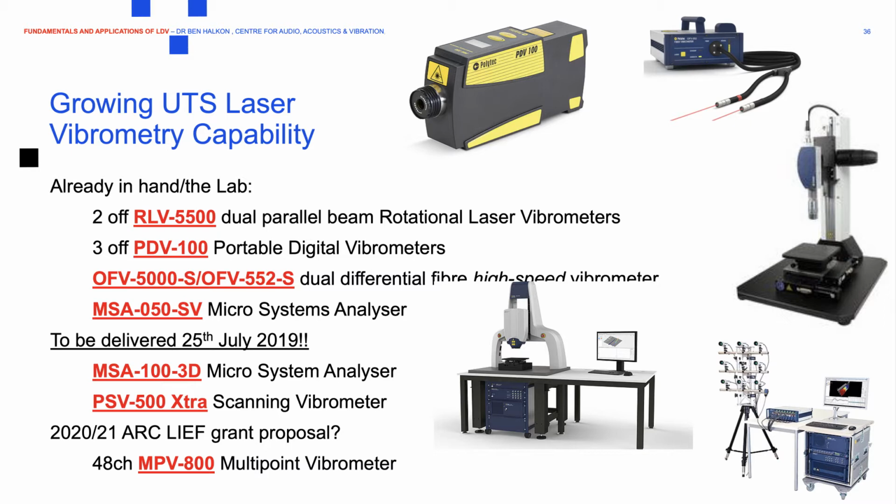So I mentioned previously that we have to take care with matching of path lengths, and we often have to treat our surfaces in retroreflective tape. With this device, it's a high powered laser, it's invisible, and infrared is absorbed by the human eye, so because it's absorbed, it's still class 2 even though it's a 10 milliwatt laser. And then we can make measurements across distances of up to hundreds of meters without any surface treatment preparation and still get good high signal to noise ratios with huge dynamic range and high amounts of sensitivity. So that's a really exciting acquisition for UTS, and we negotiated a very nice deal from Polytec to allow us to purchase that system from them.